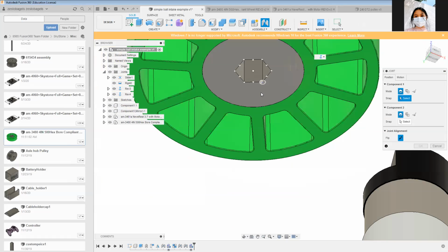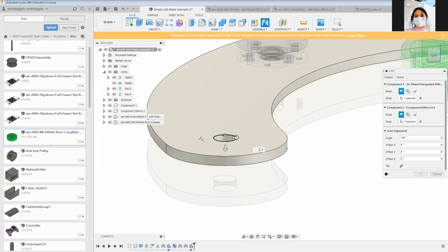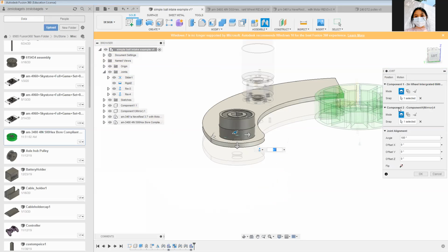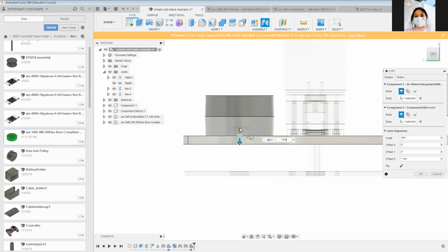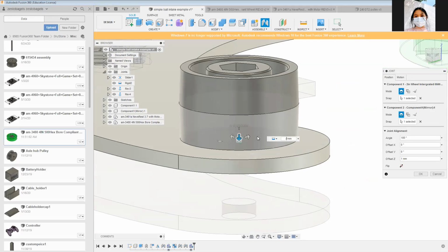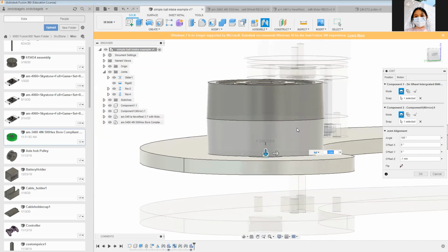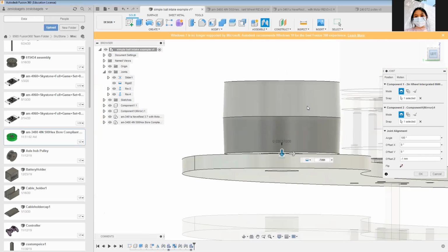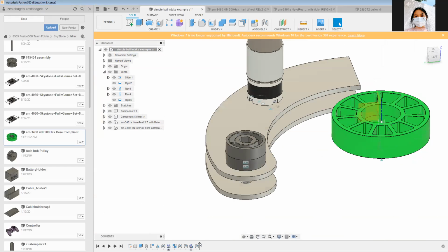Now, you can say a joint on here. And just make that rigid to make it run a bit faster. I'll just say like a 1mm offset. Oh, it's the other direction. Whoops. Now if you look at it from the side, that's the amount of clearance that I think I've used before, so I'll just use that. And then, of course, it didn't move it.